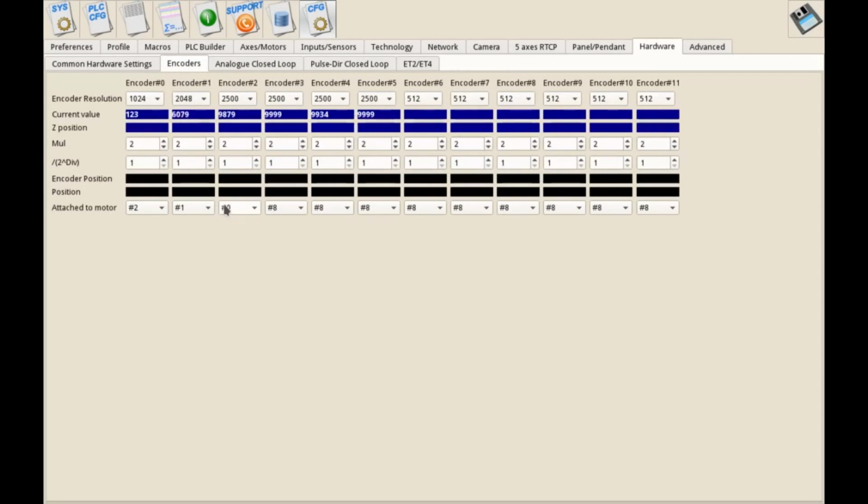In this case, we haven't actually sent the servo on signal, so we can just move the rotor manually. The servo is currently off, so you can just see the encoder values as they are changing very rapidly. Nothing is impeding them. There's no resistance, nothing like that.